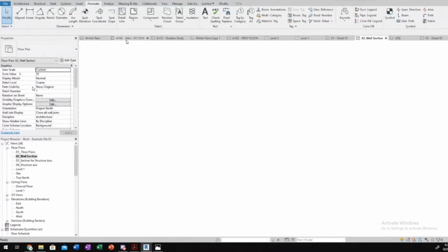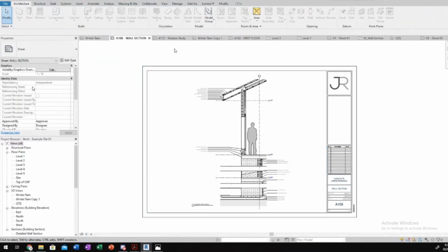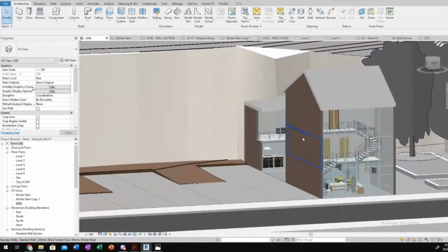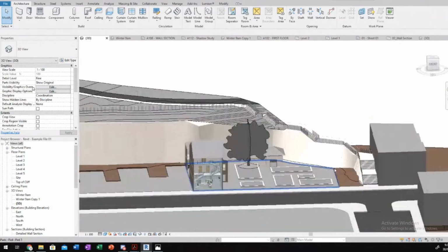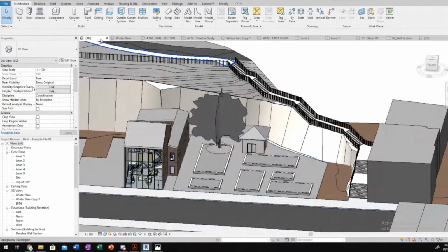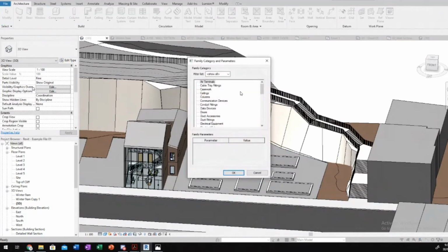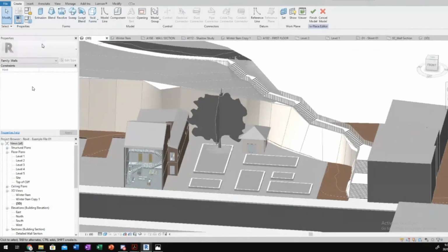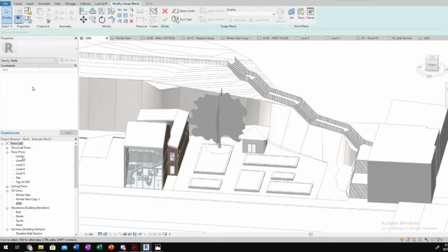And then lastly, I just want to show the possibility of doing some funky modeling in Revit too. So if we go back to this model, I'll just use this space as an example here. So for example, you can model in place mass. Say you want to make a wall that's curved in a bit of a weird way. You can choose wall here, and it gives you these tools again. So you remember that extrusion that we did before, we can do that. But I'm going to show you an example, this sweep blend, which is quite an interesting tool.